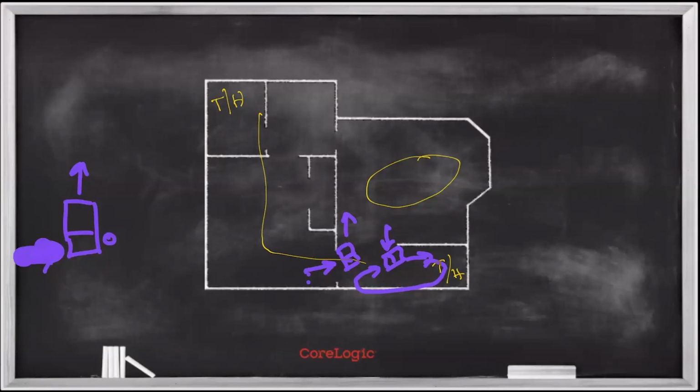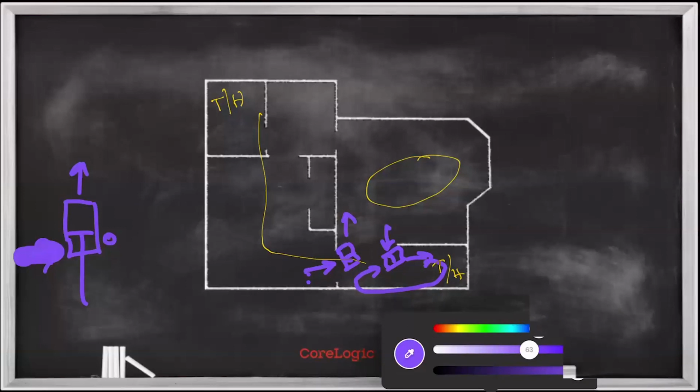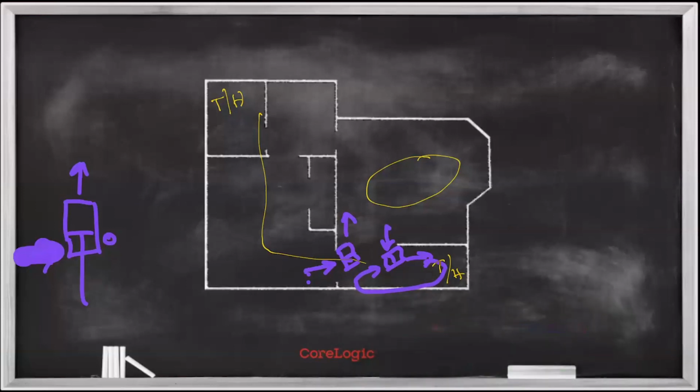Now, your new low profile air movers, technically you could flip them on either side and go counterclockwise if you wanted to. Your axial air movers don't draw from a neighboring room, right? The air goes straight through an axial air mover, so this installation wouldn't necessarily work with one. I'll draw that in a different color so we can differentiate. If I were to use an axial air mover here, it's going to draw from the same room and drop to the same room. It's not going to create that room-to-room circulation.